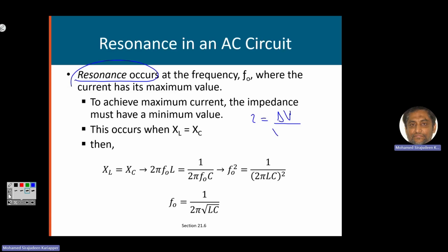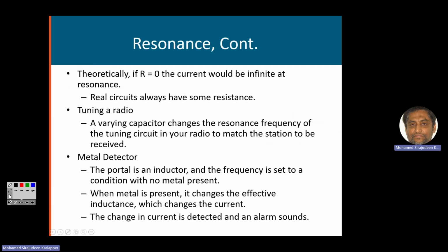We only change the frequency of the source. When you change the frequency, XL and XC will change. That means the impedance will change.